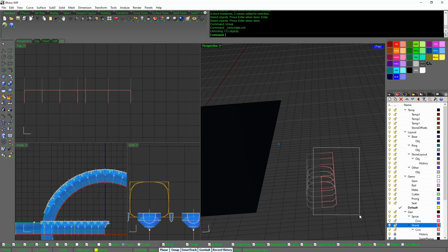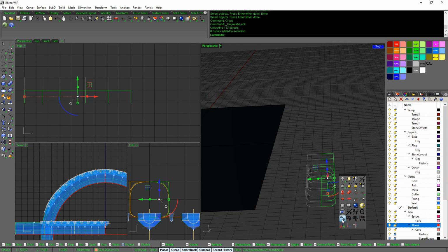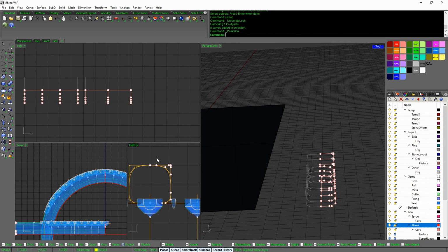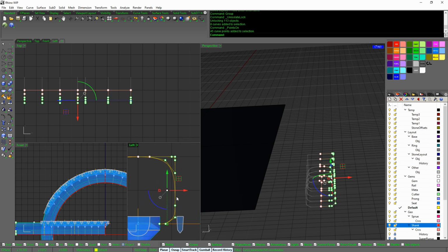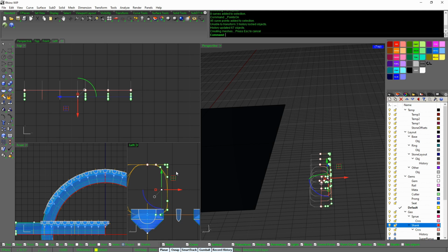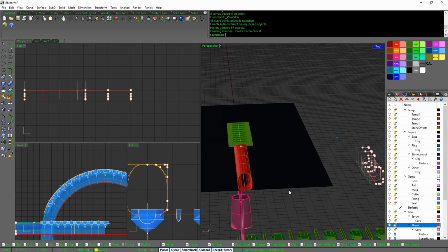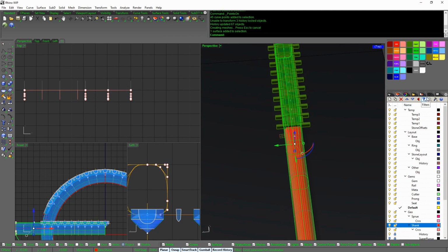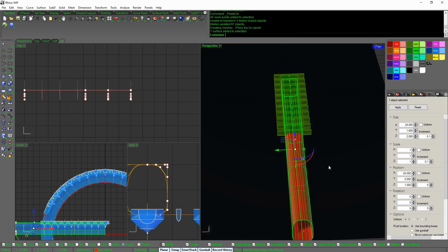I'm just going to grab all of these guys and turn their points on. And we just want these. So we're at 2.2. We need to go to 1.3 with a 0.15mm offset so our stones don't overhang. 2.2 minus 1.6, that is 0.6. Half of that is 0.3, so negative 0.3 will give us a shank that is 1.6mm wide.